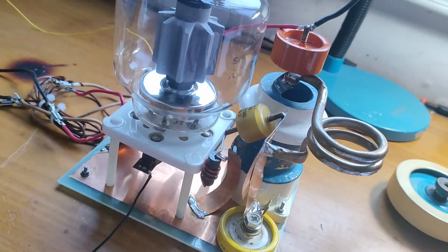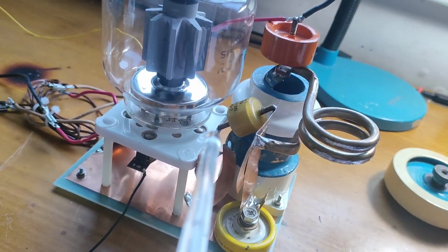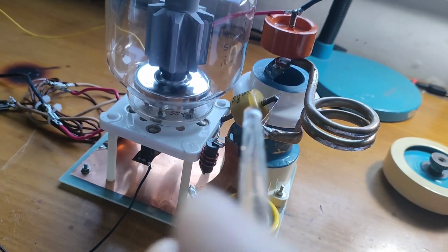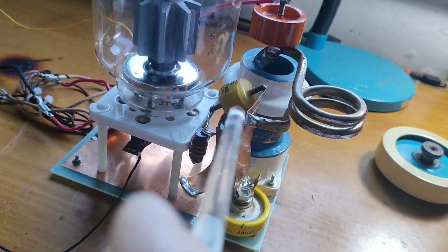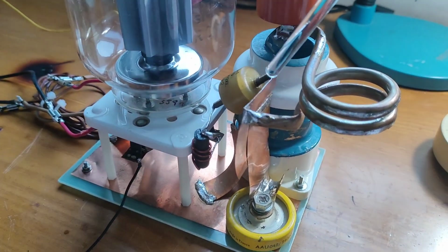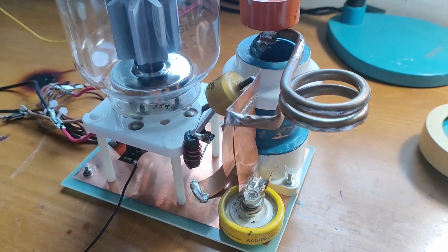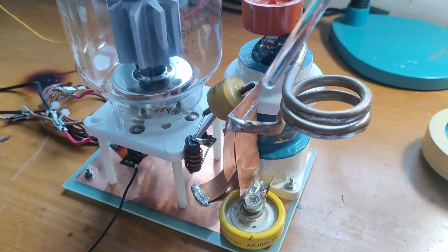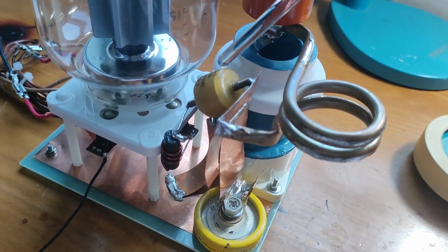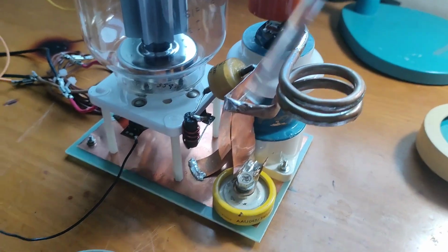Also, do not use those blue small capacitors, which you can easily see in some switch mode power supplies, in such a high power RF generator, because the grid feedback capacitor also needs to withstand high reactive power. Once I tried to parallel that kind of blue small capacitors, which are around 1 centimeter in diameter, not a very small one, and they got burned in a few seconds. So I simply use a 12 kilovolt 510 picofarad ceramic capacitor in series with the grid feedback loop.